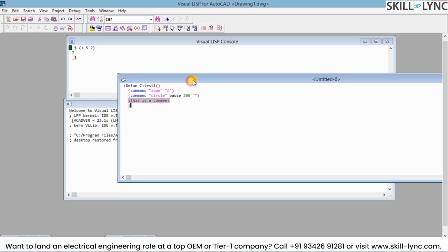So this is the major advantage that you get in a Visual LISP editor, wherein we can see how the different types of data characters you're using, whether it's a system variable, a string, an integer, or a user-defined function, are all showcased by the differences in icons or font color. As you can see here, system commands are all highlighted in blue. The text is in blue for all system-based commands.